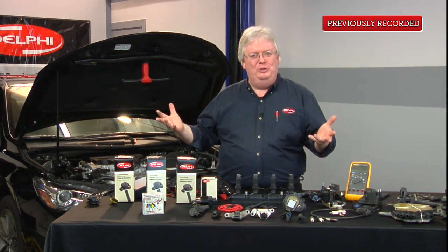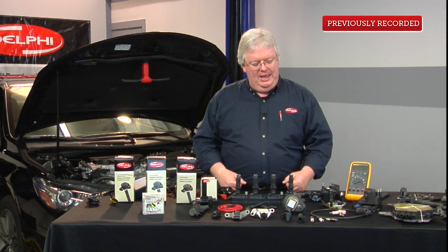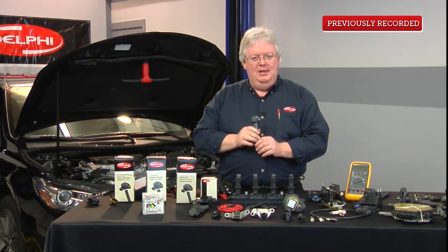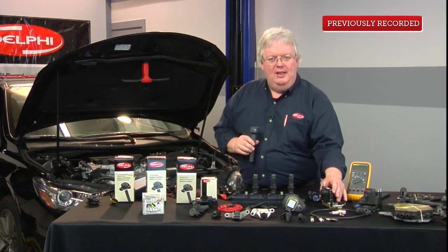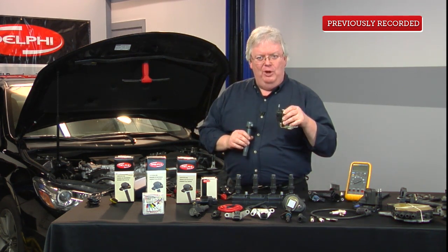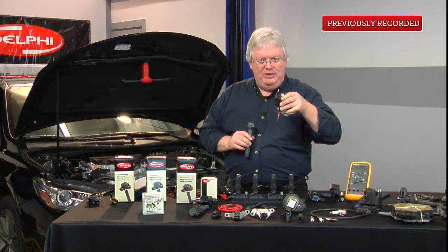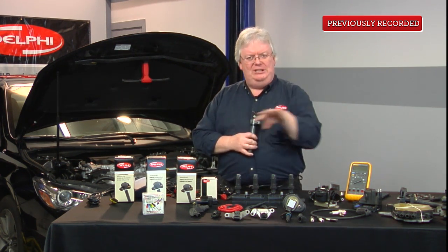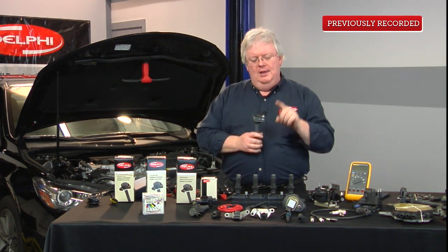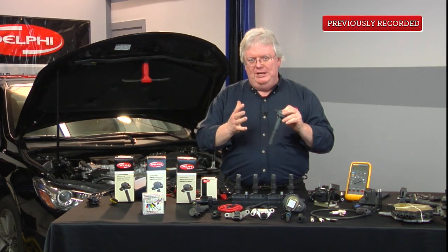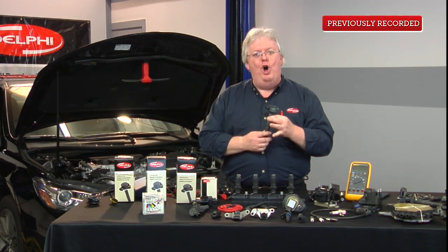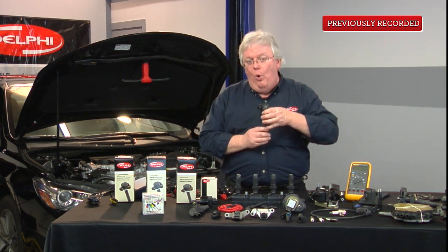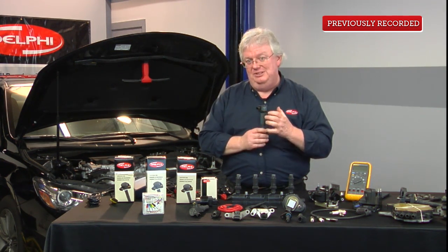The dwell, we used to call it with the old point condenser days. And because there is one coil per every spark plug, they don't always have to have the coil off and on continuously for all 6 or 8, like the old distributed systems. So therefore, overall current measured over time is much lower. And that's why, because of 2 reasons: these don't turn on as long or as often as these older coils, and they're not oil-filled tower coils to dissipate some heat.